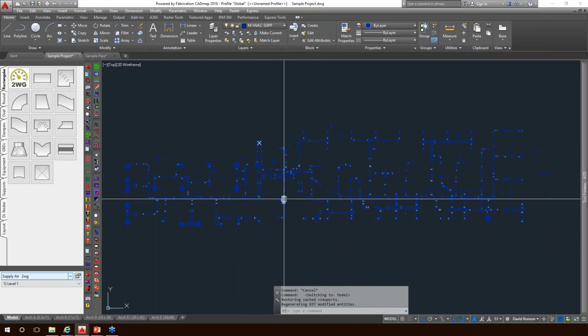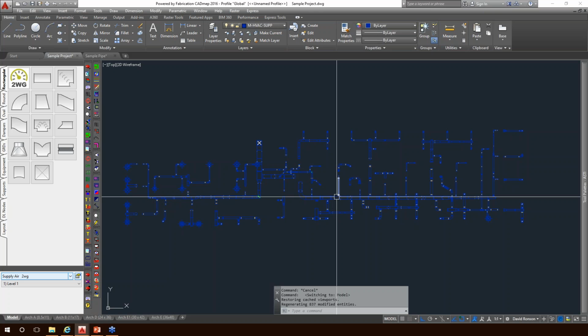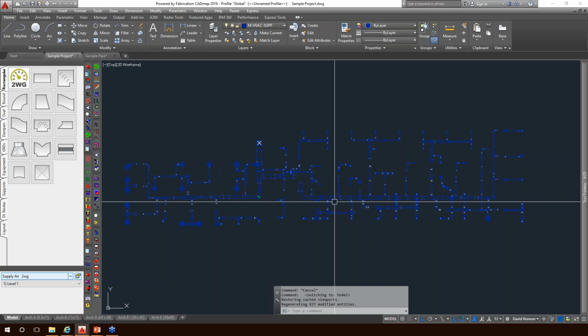One of the problems with texting in model space is that when you send this out to a Navis file, you get a whole cluttered mess of text, okay? And that text can collide with things that we don't really care about. So next, we're worried about what setting do I have in Navis to not bring in my text, or do I need to turn that layer off prior to sending it to Navis, or I can turn it off once it's in Navis. Well, we can take care of that by not even putting annotation in model space at all, okay?